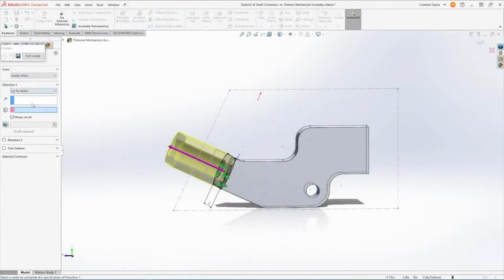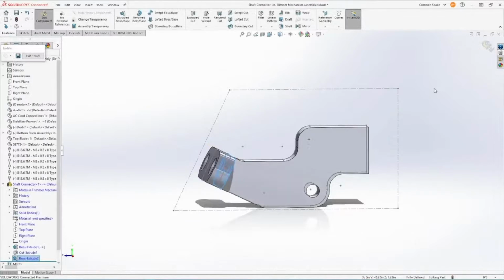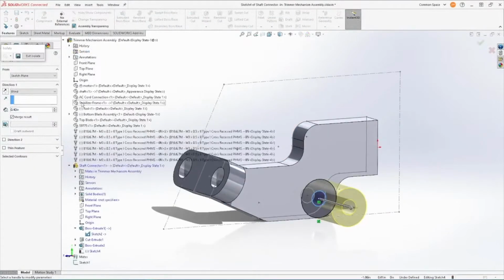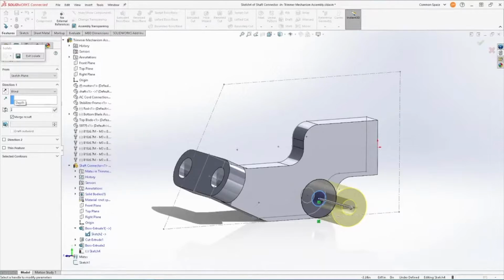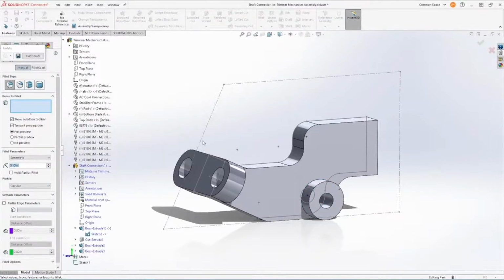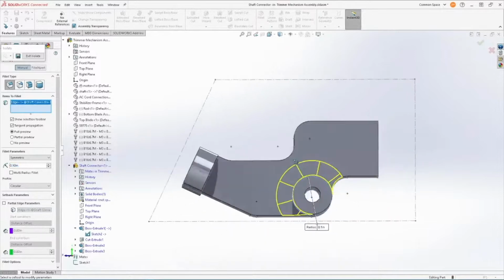So let's go ahead and extrude this, and I'm going to extrude that up to the vertex from our previous sketch there to terminate this feature. All right. So we're going to add one more circular extrusion just to hug that stabilizing rod a little bit more. And we're going to use that handy S key again. But you'll notice this time we don't get sketch options. We get options for features like fillet. So we're adding a fillet.